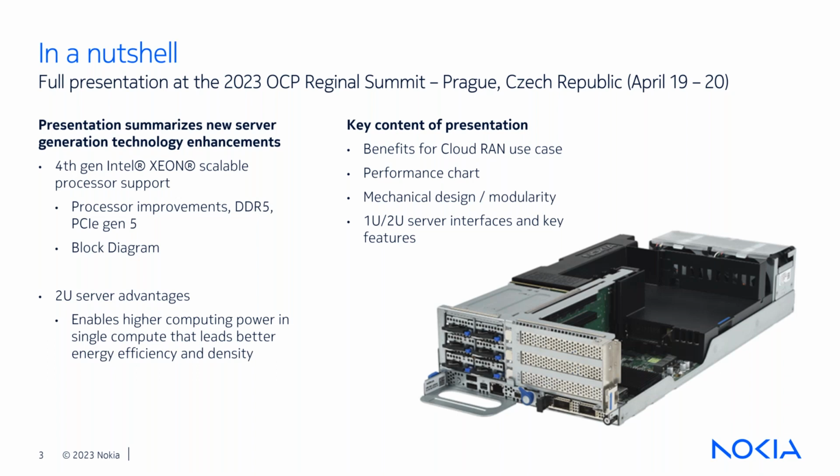Those original chassis values were more just limiting the total power of the chassis to the power capacity of the PSUs that we selected originally, and actually from the beginning the chassis can host higher power single sleds, but then of course you need to balance it so that you don't exceed that 2 kilowatt PSU limitation, or if you are using a 1.2 kilowatt PSU, which is one alternative in that form factor, then you should not exceed that.